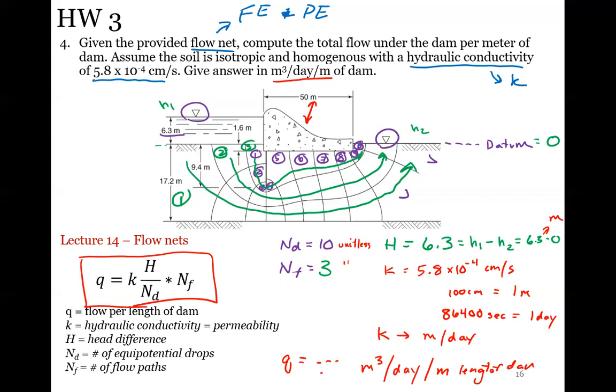But then like the other one before, how it was coming out of the paper, like a total length of it. In this, since we're not given that, we just put it in cubic meters per day per that length. So if we had a 2,000 meter long dam in this direction, then we could find the total flow by multiplying that lowercase q times that total length.